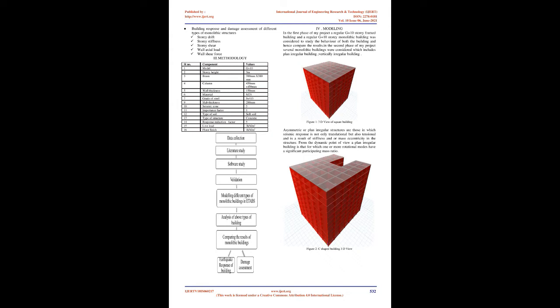On comparing the normal framed building with monolithic building construction, and conducting several analysis methods, it is clear that the monolithic building is much more rigid and has less vibration. Fundamental time period in seconds: 0.195, 0.2010, 0.176, 0.182, 0.177, 0.184, 0.187, 0.178. Figure 3: I-shaped building, 3D view. PI 1 to PI 8. Figure 5: comparison of time period of monolithic plan irregular buildings.